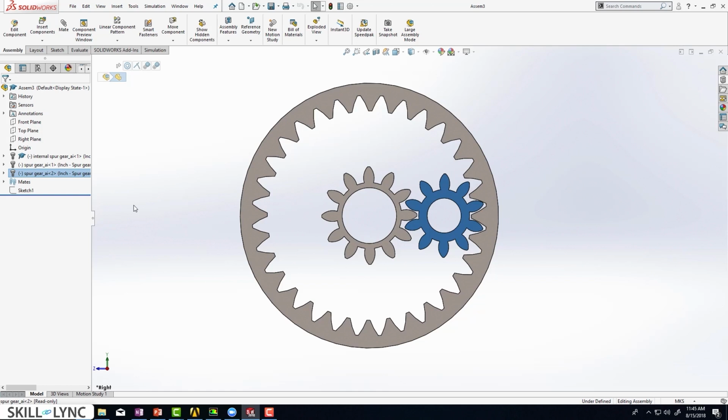Now, we can start by creating our own gears in SolidWorks by sketching and then using the extrusion operation. That is unnecessary because SolidWorks provides a library of gears according to different standards, and we can use this for our purpose, and that's exactly what we are going to be showing you in this video. In this case, we need a sun gear, a planetary gear, and also a ring gear, and we can just use the design library to import the appropriate models. Now remember, the internal gear is basically an internal spur gear, whereas the other gears, the sun and the planetary gears, are just spur gears.